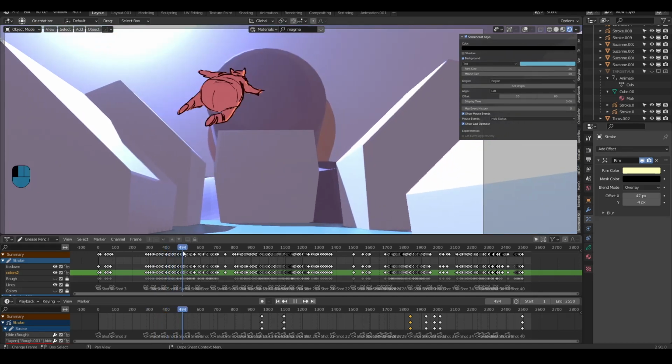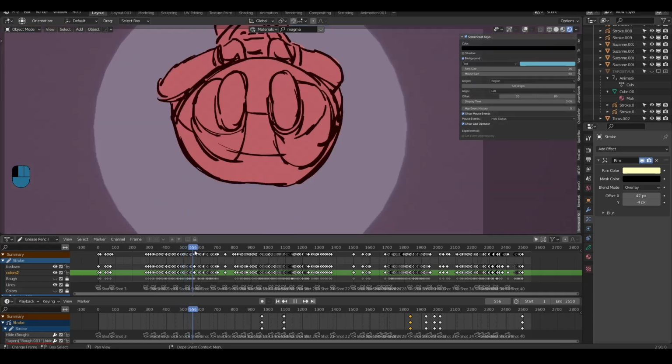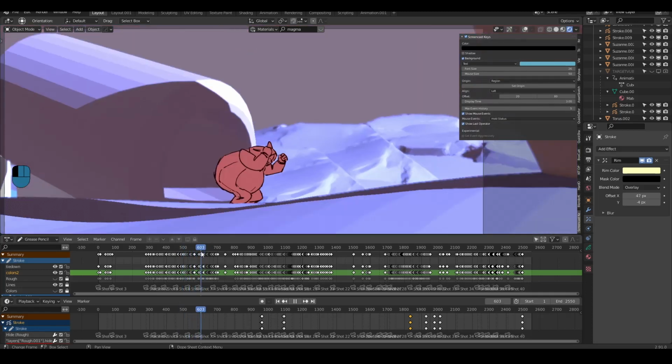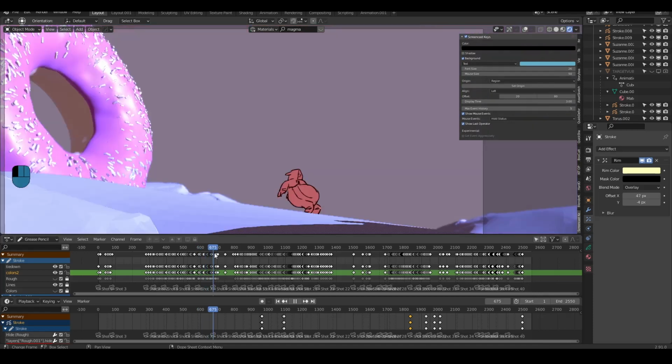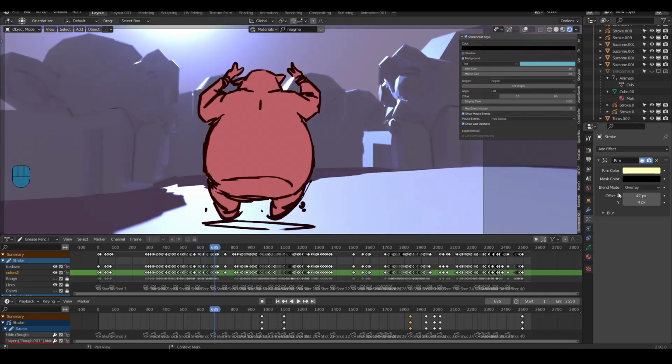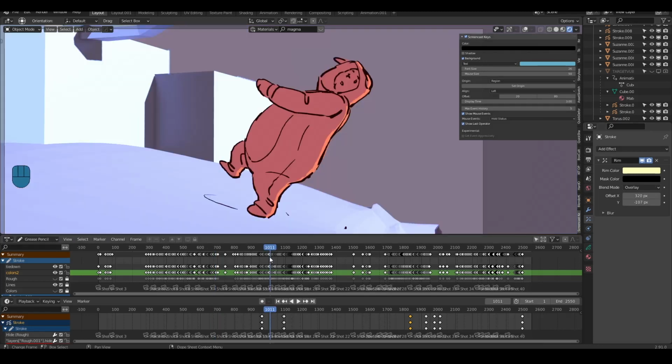Again, it's not too bad, but by default in object mode they would be way more consistent here. So again, it's just a case of if you want it, you have to key in some extra keys to make it work. But anyway, look, it's still there, it still works. If you're going to push your object this far away from the origin, you just have to do a bit of extra work with regards to keying some of these effects.